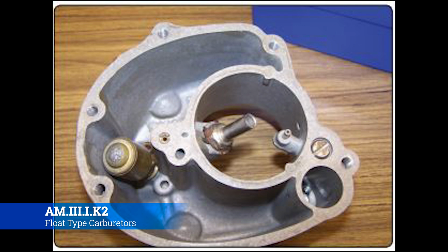Now, the way that it does that is atmospheric pressure is going to push down on top of the fuel, so you have that steady 4.7 pounds, and then because the pressure is lower inside of the venturi, it's going to start to pull on that fuel. Or rather, I guess the right way to say it is that the atmospheric pressure on the inside of the bowl is greater than the atmospheric pressure on the inside of the venturi, which then causes a differential. It pushes the fuel down and then out the jet and into the venturi that way. That is basically how the bowl works. That's what it looks like.